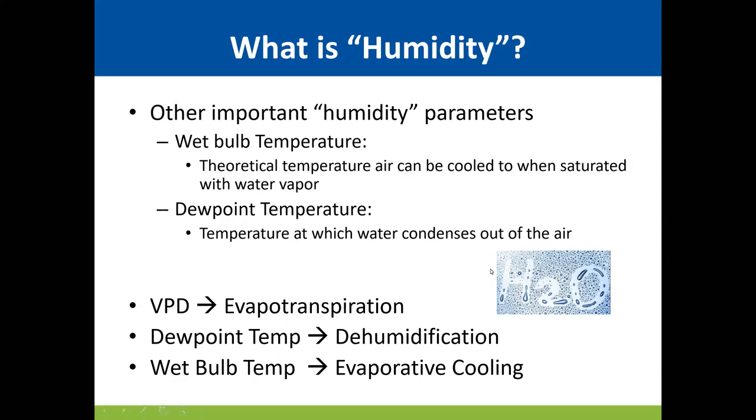So those of you who have greenhouses, say in Ohio or another cold climate, when it's really cold outside, the surface of your greenhouse cover gets cold. But you're holding a condition of, say, 80 and 70% relative humidity inside, and that water now condenses on the cold cover, and that's why you get dew forming on the cover of your greenhouse.